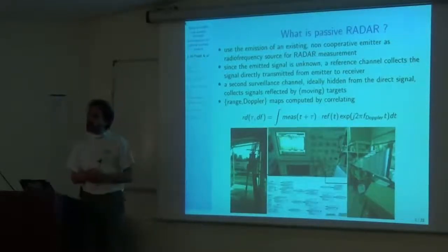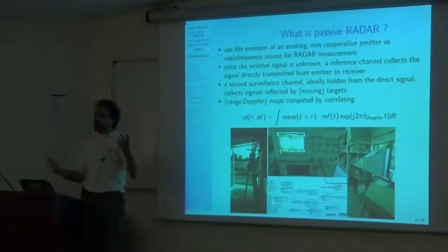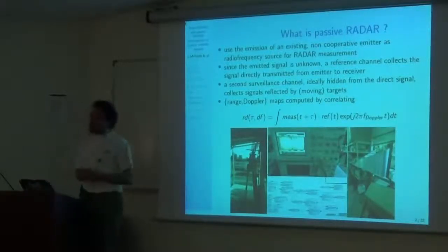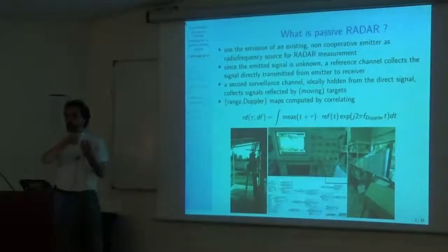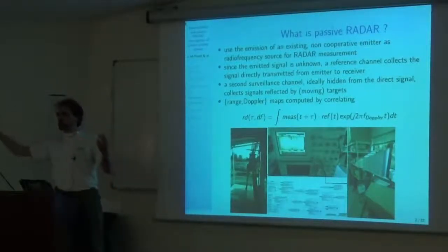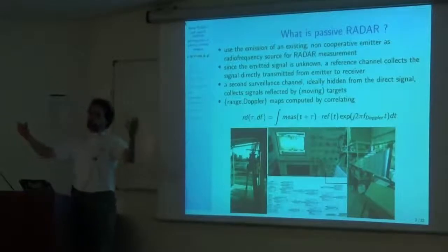Now, radar communication, you might be familiar with one-way communication where you have an emitter, a receiver, and you know that there your link budget scales as the square of the distance. You have your link budget as 1 over d squared. The problem with radar is that we are emitting a signal from a source. It bounces on a target, which we assume to be a point-like target, so 1 over d squared. And this new source is emitting a spherical wave that gets back to your receiver.